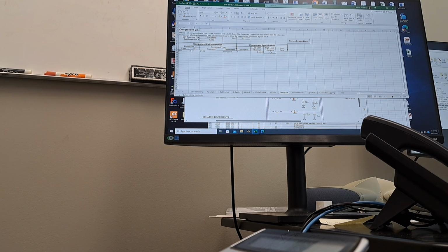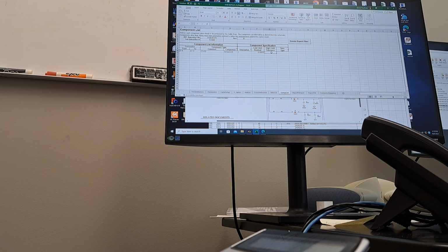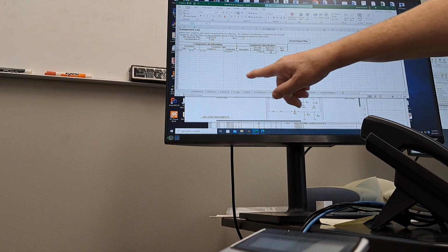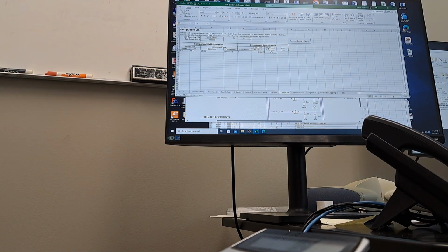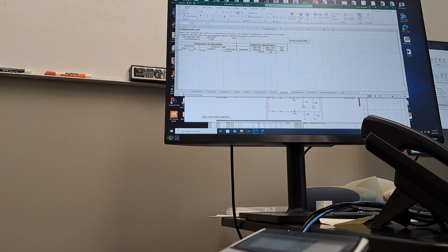I don't usually do anything lower than 20%. And we're not here to verify the capacitors per se. The main goal of cablescan is to verify that the connector pin is wired up to the board. So this is going to give me a chance to tell that J2 pin 9 is connected to something, and it's a capacitor. And if somebody puts in a grossly incorrect value, you want to know it.